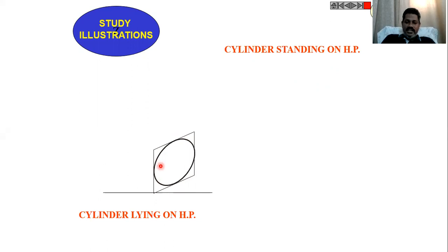When we see the circle in front view, how it looks like this, we already discussed in our previous slide. After constructing the front view of the planar surface, then project all the corners of this square with the given height of the cylinder. Then construct the other face of the cylinder in the square with the same procedure.